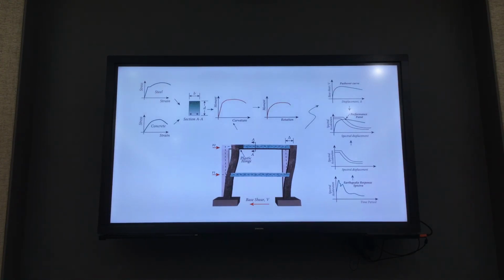That's my point exactly. Once we do the nonlinear dynamic analysis, you know everything about the structure. So that possibility is already in the analysis results, and you can see whether it will happen or not. That's why we check. When we do the performance evaluation, we don't just check the overall response. Every member, every column, every beam is checked to make sure that doesn't happen.